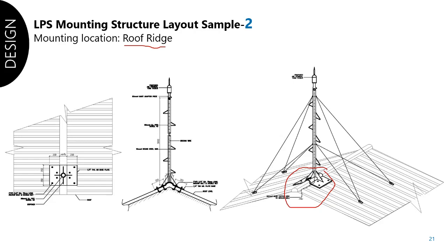So this is how I design. Usually for this small inner ridge, in older designs it was just 3 meters high, but now I'm using a 5-meter-high lightning pole for my air terminal. Most of it is greater than 5 meters. I'm not using smaller sizes like 3 meters.